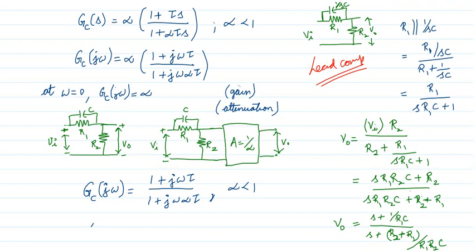Okay, so this is a lead compensator circuit. For the lead compensator circuit, what I am doing is I have to cancel out this alpha. So I introduce an amplifier whose gain is 1 by alpha. What happens when this signal comes here? This alpha and this 1 by alpha will get cancelled out. So we will have V naught as this expression. I have removed the alpha, right?